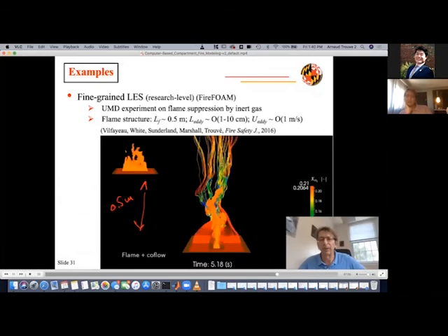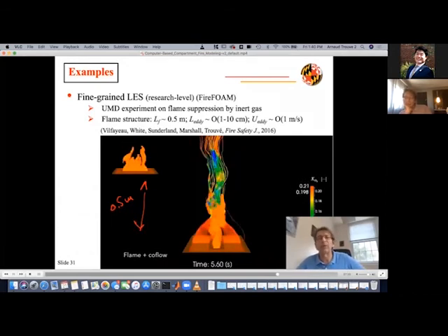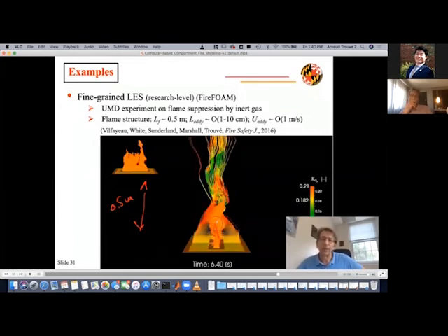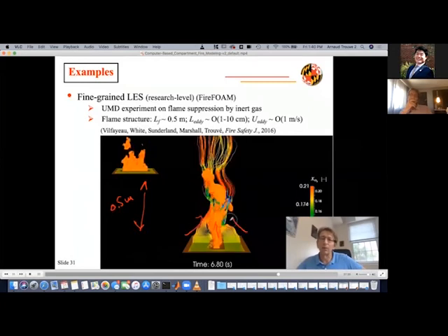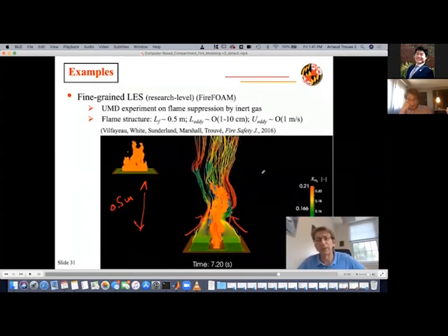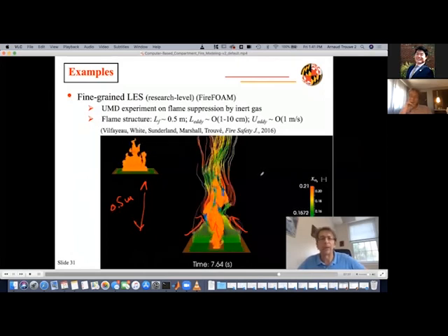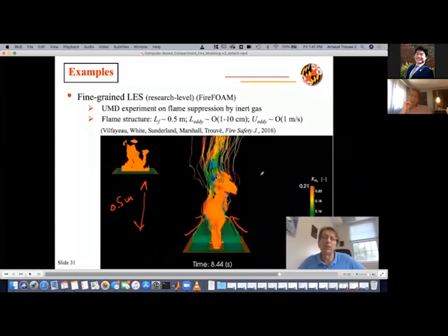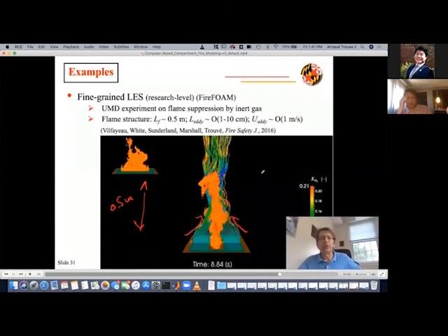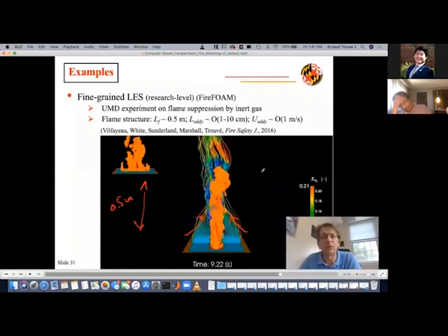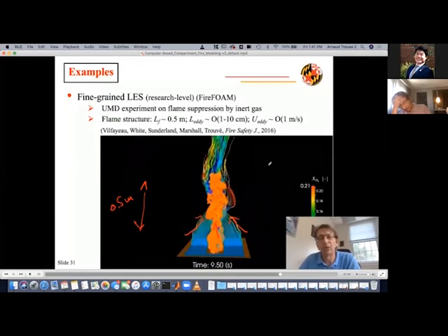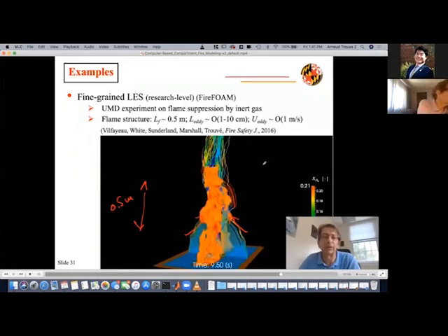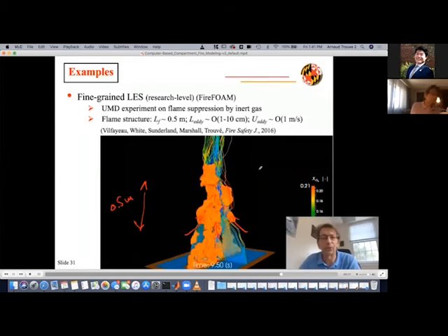So this is a methane air flame. Well, no, I shouldn't say methane air. It's a methane air nitrogen flame. So you have methane injecting in the center of the system. And then in the co-flow, you have injected air with an increasing amount of nitrogen. And when the amount of nitrogen present in the air nitrogen co-flow is too large, then the flame extinguishes because of oxygen starvation. So correct simulation of this oxygen limit for extinction is key to being able to describe extinction of an underventilated fire. The oxygen starvation process is the same.